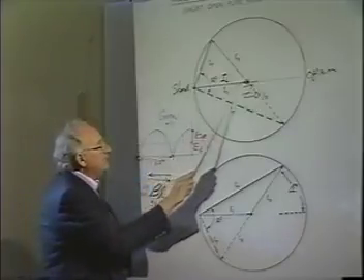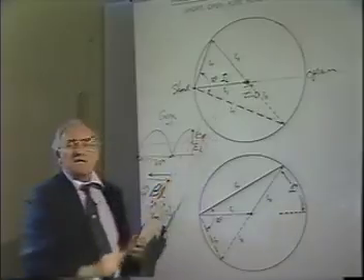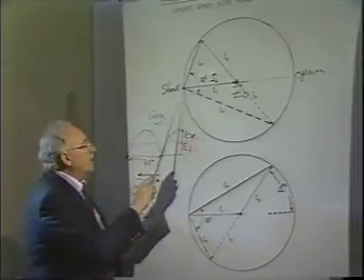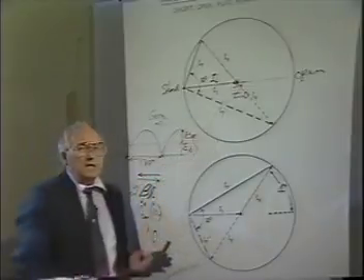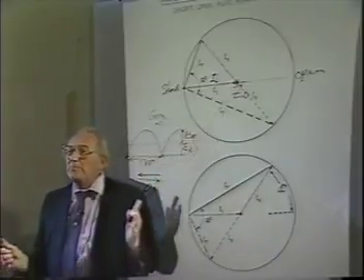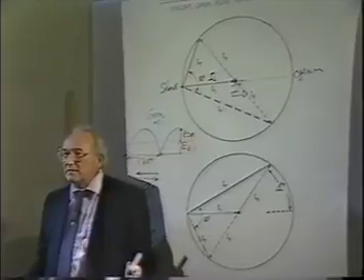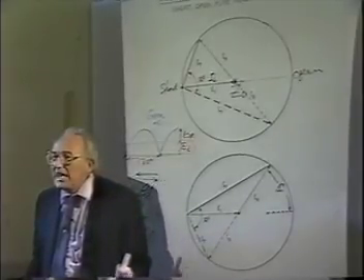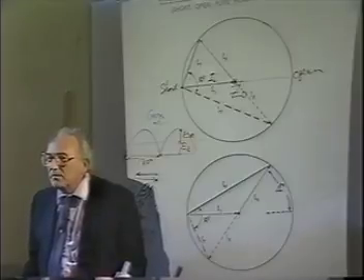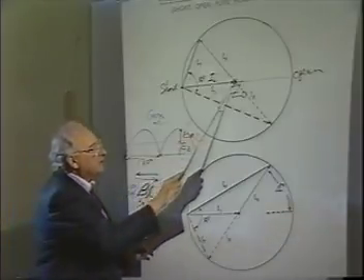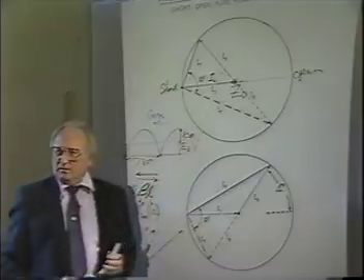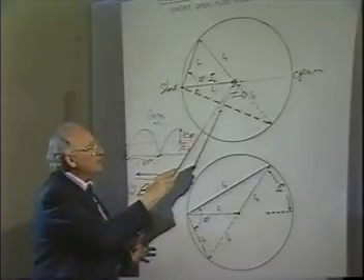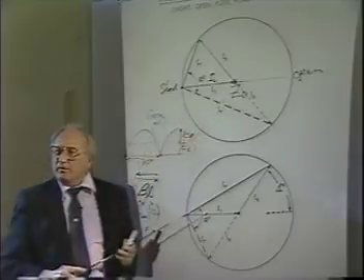This is in phase here. Since these two are in phase, it tells you something very definite about the impedance. That anywhere along this line, impedance-wise, is and represents only a pure resistance. But the pure resistance is always what value? Less than Z0. It will be equal to Z0 at this point. Anything from this point to this point over here is between Z0 and a short circuit.